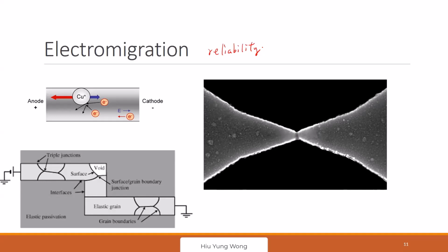But if you do a realistic design, not just DRC and LVS, you need to go through all the corner checks. You need to go through all the reliability checks and other things, even the EMI check, right? So what is reliability? When you have a very huge current, the electrons are running so fast they knock off the atoms. The atoms are supposed to be still, right? And then you pass a big current, and the electrons keep knocking the atoms off.